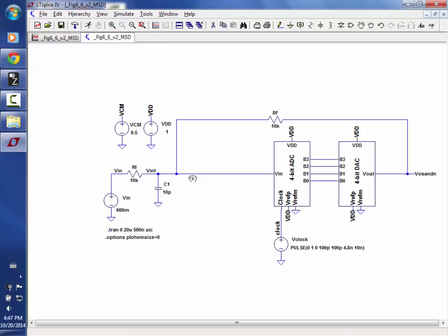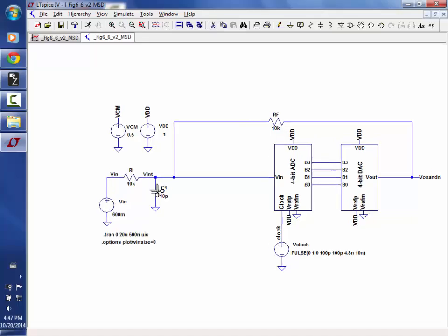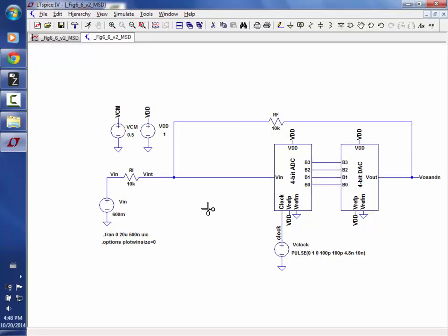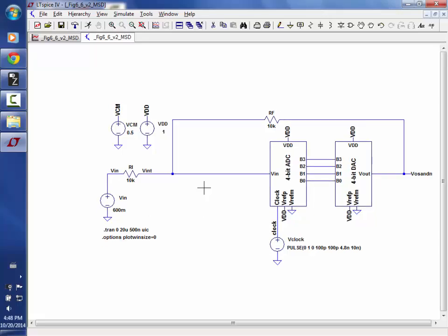So what I'm going to do is replace this integrator here, the passive, with an active. And when I do that, it's going to give me a negative forward path, so I'll get negative feedback here. So the output will be inverted from the input. So we'll get rid of this. This is what I said, people don't use the passive, and the only time I've seen it is with 1 bit, and maybe this is why.